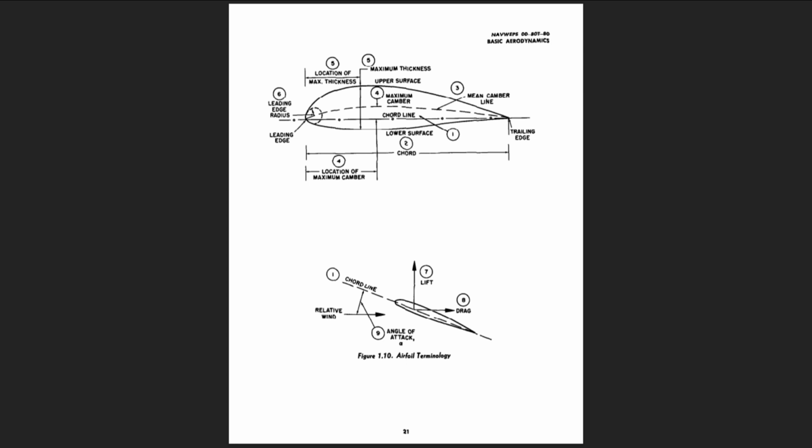6. The leading edge radius of the airfoil is the radius of curvature giving the leading edge shape. It is the radius of the circle centered on a line tangent to the leading edge camber and connecting tangency points of upper and lower surfaces with the leading edge. Typical leading edge radii are 0, knife edge, to 1 or 2%.